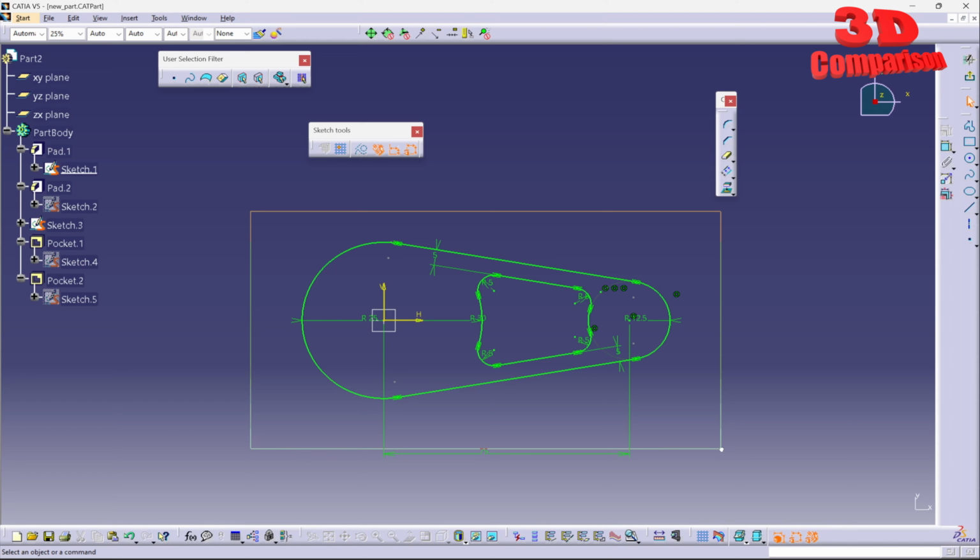Welcome back to a follow-up video. So this will be regarding the problem with the fillet. And as you can see over here, if I enable the edge fillet and I want this to be applied on the top edge and also over here, since you have this seam line added within the extruded circle, we're going to have the following update problem over here.